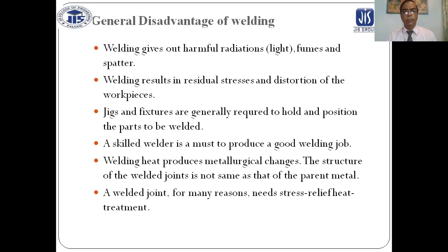General disadvantages of welding: welding gives out harmful radiations, X-rays, ultraviolet light, fumes, and spatters. Welding results in residual stresses and distortion of the workpiece. Jigs and fixtures are generally required to hold and position the parts to be welded.